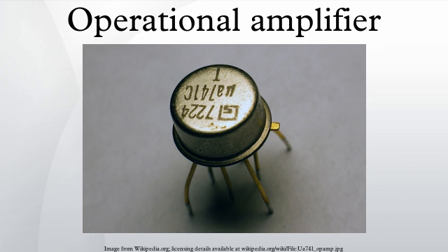The first stage consists of the matched NPN emitter follower pair Q1, Q2 that provide high input impedance. The second is the matched PNP common base pair Q3, Q4 that eliminates the undesirable Miller effect. It drives an active load Q7 plus matched pair Q5, Q6. That active load is implemented as a modified Wilson current mirror. Its role is to convert the input current signal to a single-ended signal without the attendant 50% losses.